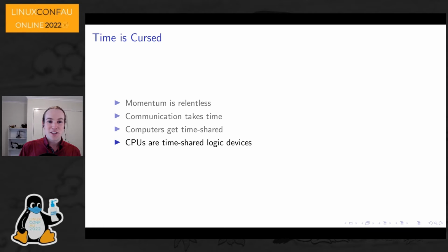Unfortunately, CPUs take time to do anything, and things have a habit of happening all at once. The more interrupts you want the CPU to service, the more likely it is that your interrupts will collide with each other and one will get delayed or missed. The more strictly timed code you try to write, the less of your code will be on time. I mean on time in the strictest hardware sense here, running a specific CPU instruction at a specific instant. Bit-bashed protocols and physics experiments. The promise of time sharing of a CPU is incompatible with the promise of handling multiple unpredictable events on time every time. The solution doesn't exist to be written down in a software framework.